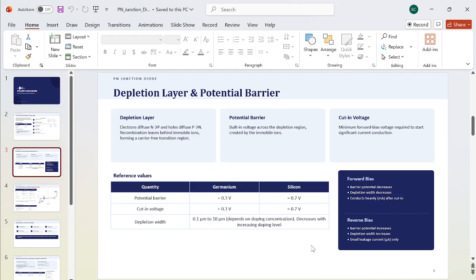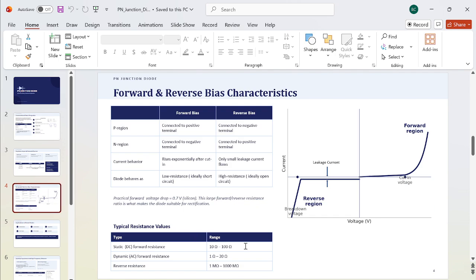significantly lower current, which is basically known as the leakage current, that flows through the device, that is of the order of few microamperes. And that leakage current is actually because of the thermally generated minority charge carriers, so that is dependent upon the temperature of the device. Now here I have shown the characteristics of the PN junction diode. This first quadrant part is for the forward bias operation of the PN junction diode, and this is for the reverse biased operation of the PN junction diode.